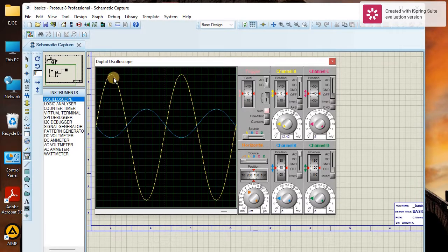So same thing, we can try to count these from here to around there. So this is 1, 2, 3, 4, 5, 6, 7, 8, 9, 10. So 10 times 2 milli, we should get 20 milli over 1,000. That is 2 over 100, and 1 over 50, and your frequency is the inverse, which is 50. Okay, so that is that.